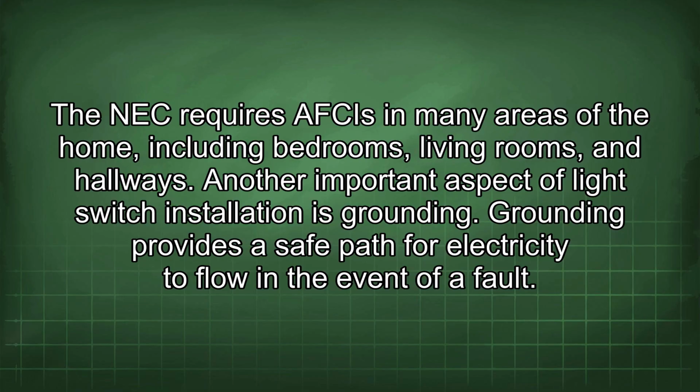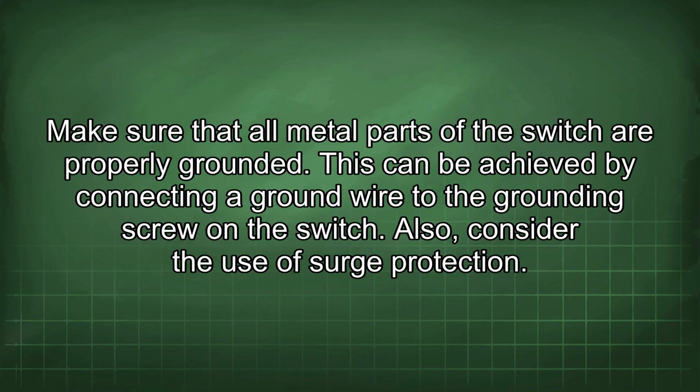Another important aspect of light switch installation is grounding. Grounding provides a safe path for electricity to flow in the event of a fault. Make sure that all metal parts of the switch are properly grounded. This can be achieved by connecting a ground wire to the grounding screw on the switch.